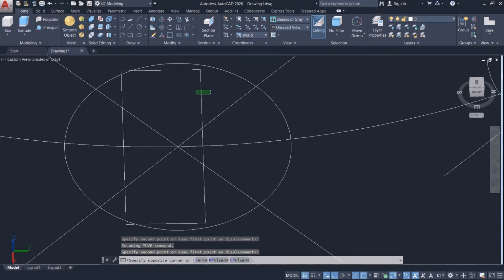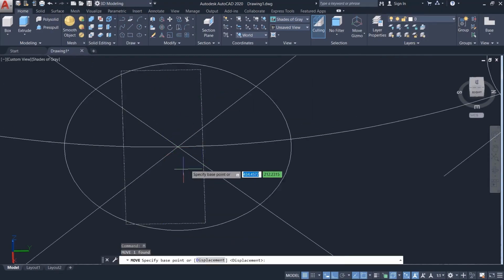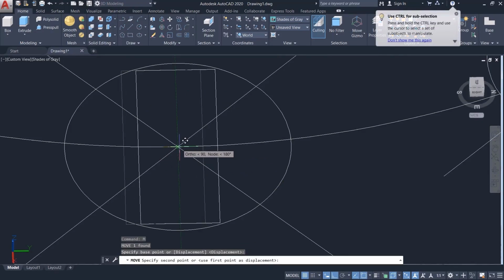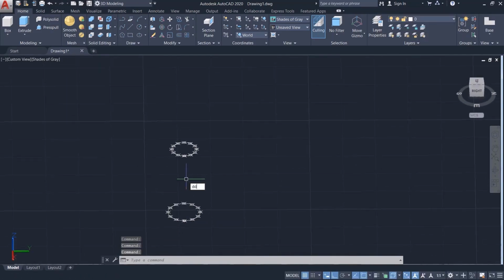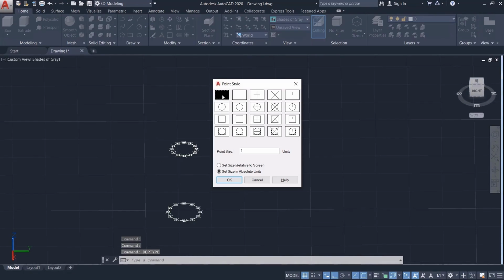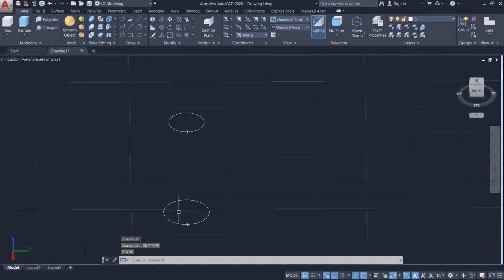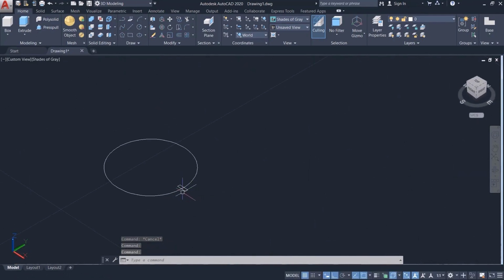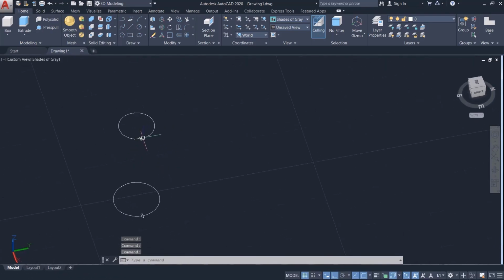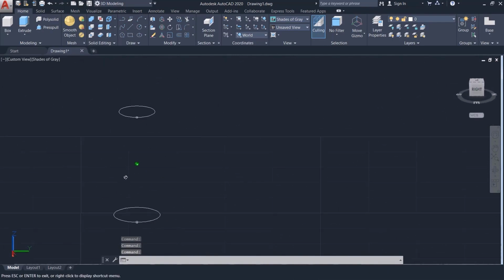It placed it in the wrong spot. Enter. Let me put its center on the center of this point. Alright. Now, using the p-type view, I'll remove the points. Basically, I'll shrink their size so they're not visible. You see, now we've drawn the lower section. It's 35 centimeters thick, and its width is 1 meter and 17, the concrete column. On this side, it's again 35 centimeters, but on the other side, it's shrunk to 92 centimeters.